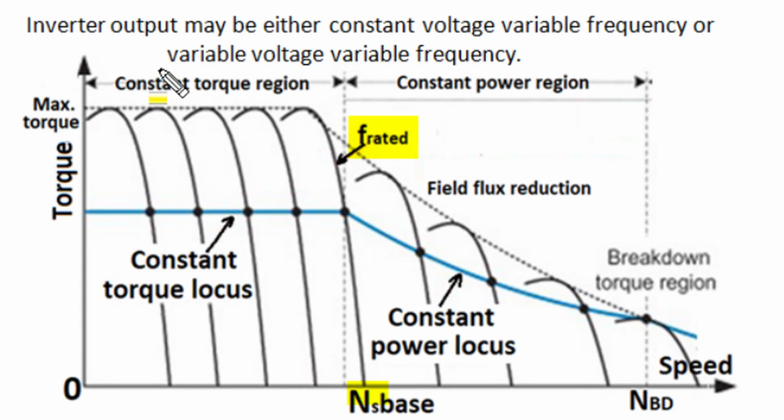And when the voltage to frequency ratio of the supply applied to the stator is maintained constant, then the magnitude of flux in the air gap between stator and rotor also remains at a constant value, and as per rotor current capacity and constant flux operation, the motor has a constant maximum torque production capacity, but reduced synchronous speed of the rotating magnetic field.